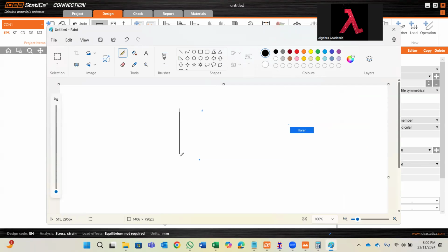The one which you're talking about, I'm talking about the straight, right? Okay. The one which I'm talking about, L, the one which I'm talking about like J, right? When you don't have place to maintain the sufficient embedment length, the embedment length is going to be measured from here to here. So this is also part of embedment length. You need to understand.